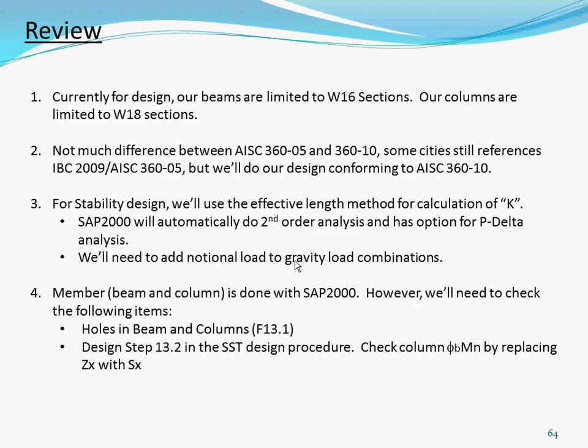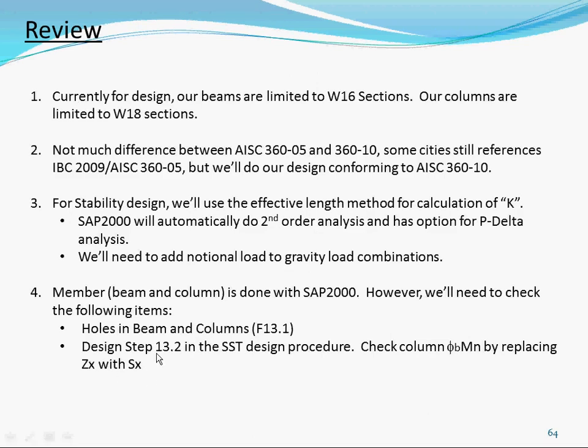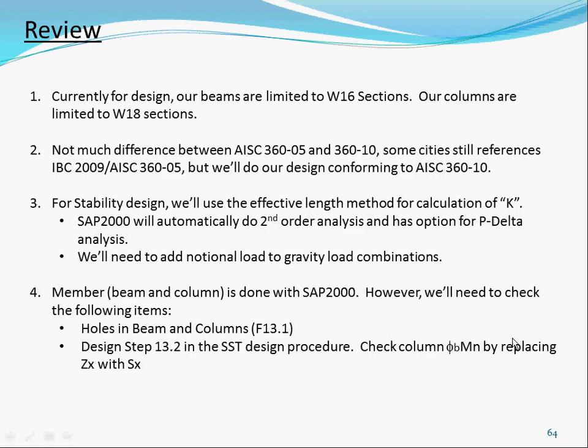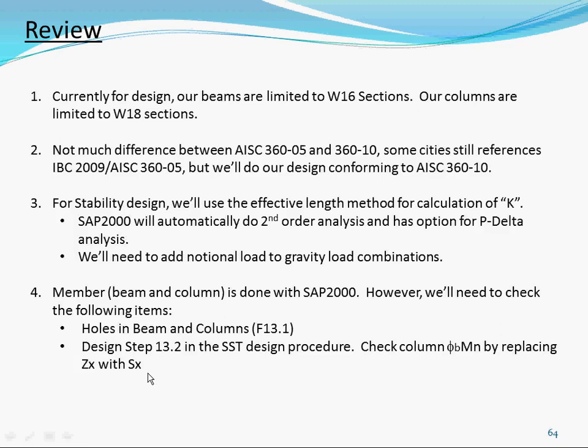Remember, for the beam and column, we'll be doing the design using SAP. However, there are some checks that SAP doesn't do, which we have to do separately, which is the holes in the beam and the column. And then for design step 12.2 in the design procedure, we'll have to check that moment capacity, the phi Mn, by replacing Zx with the Sx.